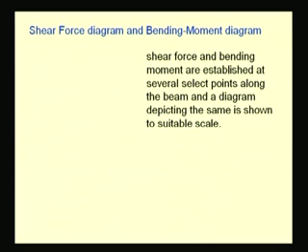We have the shear force diagram and the bending moment diagram depicting the shear forces and the bending moment, which are the predominant internal forces in a beam along the entire length of the beam for a particular loading condition and supports.